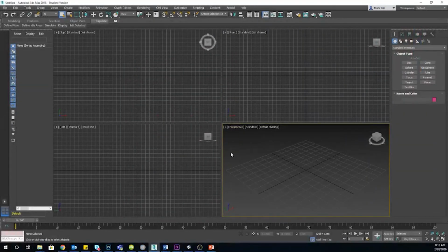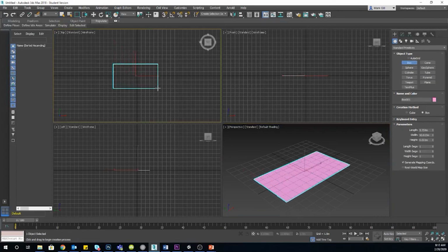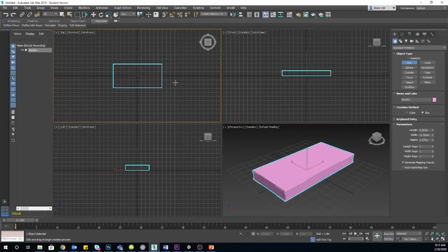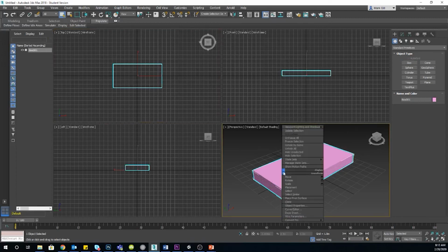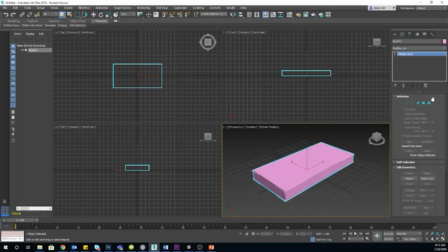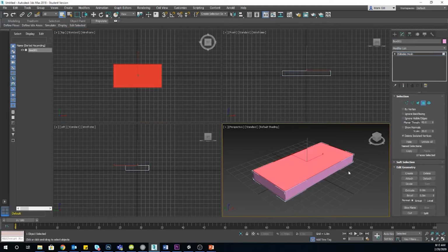And I've got the 3D Studio interface. Now, I could have started just like I did with the last video, and create a box, and then I could convert this box into an editable mesh, go into my editable mesh, select that top polygon, give it a bevel where I make the offset bigger than the travel of it. I want it to look more like a right angle than a true bevel.